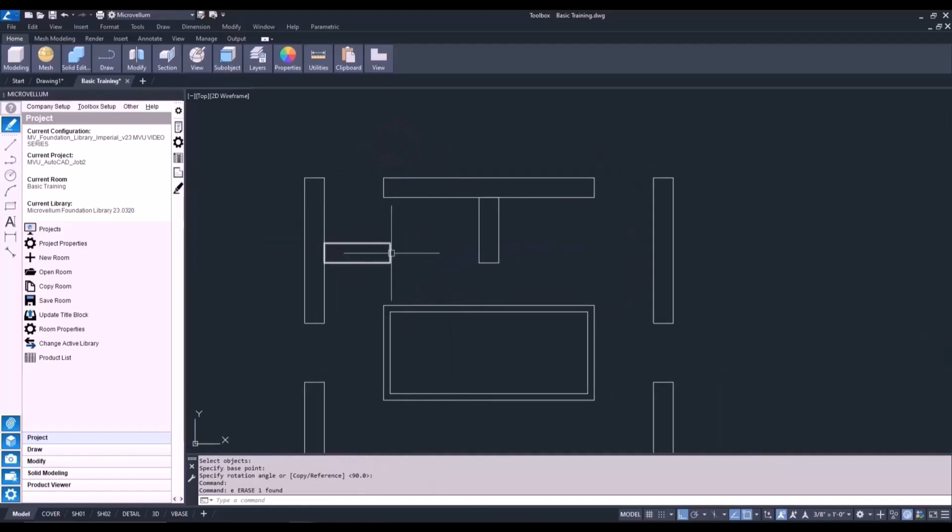See, with the rectangle, you have ways that you can stretch it and change the size of it after you have it drawn. By selecting that center grip point, you can stretch this rectangle if you need to. You turn off ortho, you can see what happens there. Let's make sure we have ortho turned on. And now we'll move our cursor over and give this a value of 10. Hit enter. So now we have that rectangle stretched 10 inches.